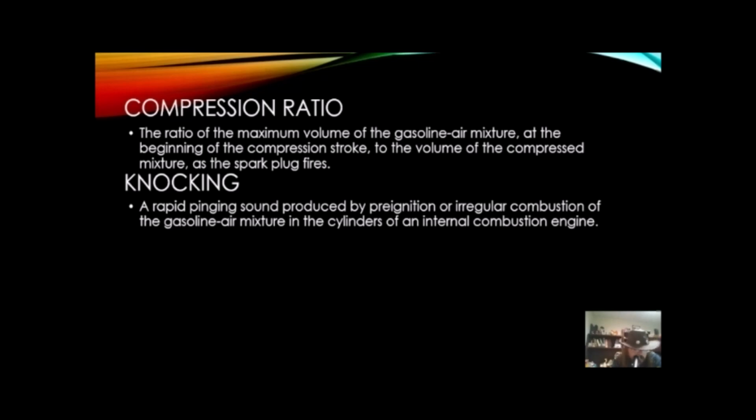All this knocking could result in just loss of power and poor mileage, but it could also pit or fracture the actual piston. So you could actually break your engine if it's knocking too violently. At any gasoline grade, the higher compression ratio you have, the more likelihood of knocking. So if you have a high compression ratio car, you often have to use a higher grade of gasoline, as we're going to see in the next slide.